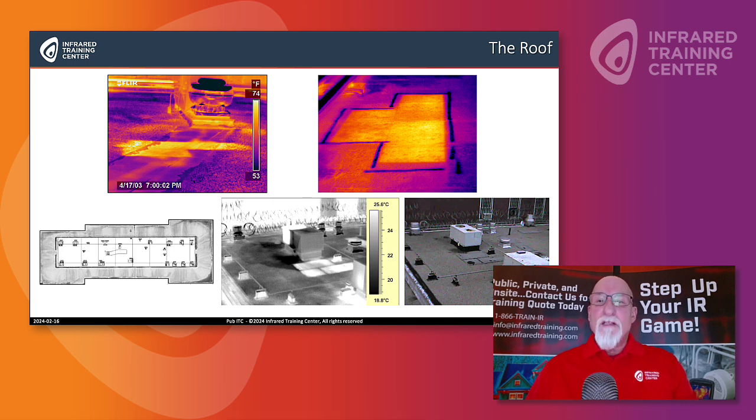I don't recommend spray paint. I would rather see you use a chalk material, something that's not going to affect the actual membrane itself, because that will affect the warranty of the roof. So you've got to be careful of what you're using there.